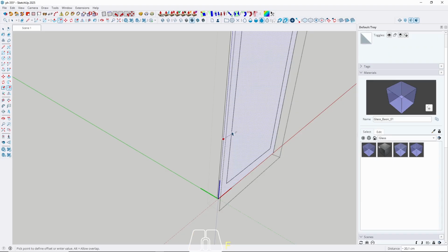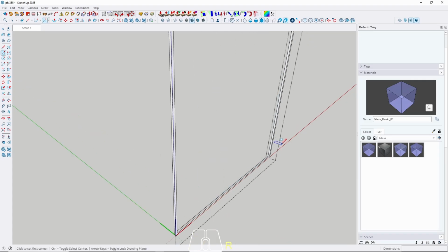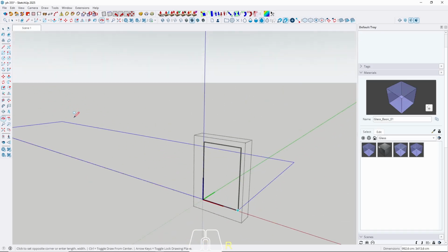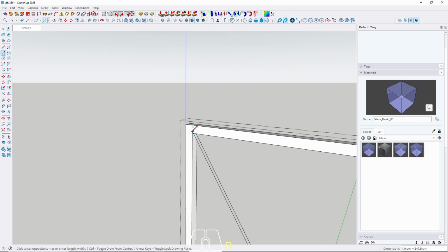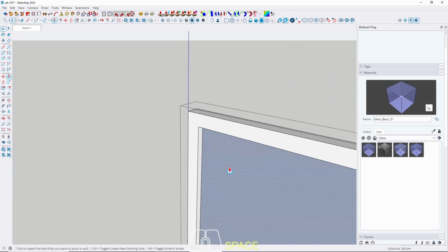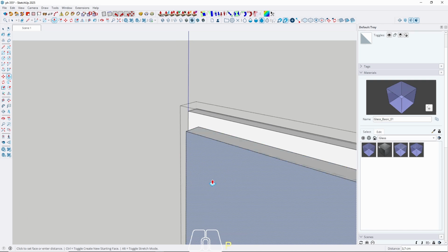So let's make a glass in the middle of this door module, 2 centimeter offset, and then a glass. The thickness of the glass, maybe you can use 8 millimeter or 10 millimeter, is up to you guys. But it must have thickness here. Minimum is 0.5.